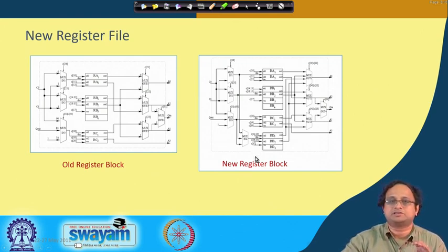The idea is that if the secret key bit is 0, then I will take only the output from this register file. So the addition which is happening even if the key bit is 0 is something I need to ignore, because that's a dummy addition operation. If I take that, then I will get a wrong result.